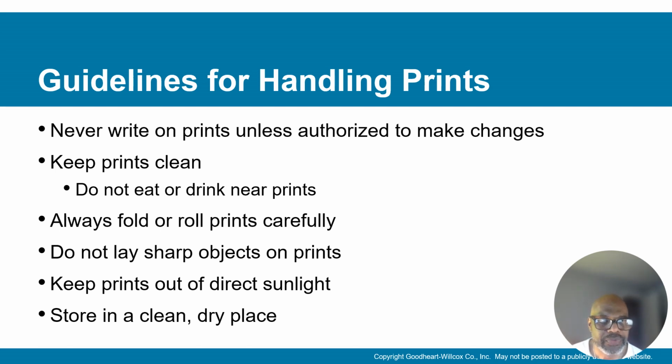So do not eat or drink near the prints. Always fold or roll prints carefully. Do not lay sharp objects on the print. Keep prints out of direct sunlight. Store in a clean, dry place. That was the very first thing I mentioned, but it's the most important thing, to keep it clean and dry, not writing on it, not putting things on it that are not supposed to be, unless you got authorization to make a change.